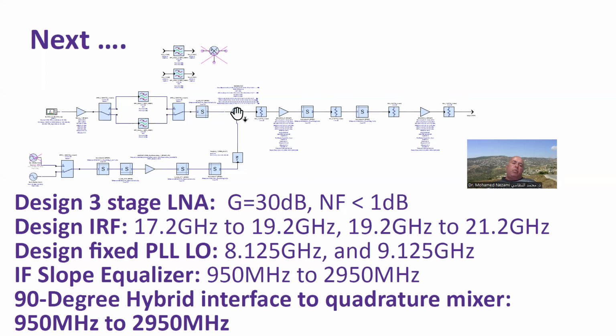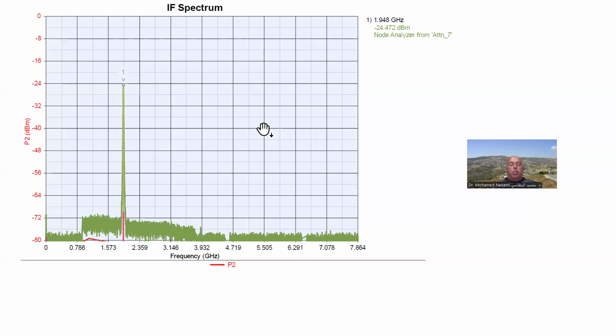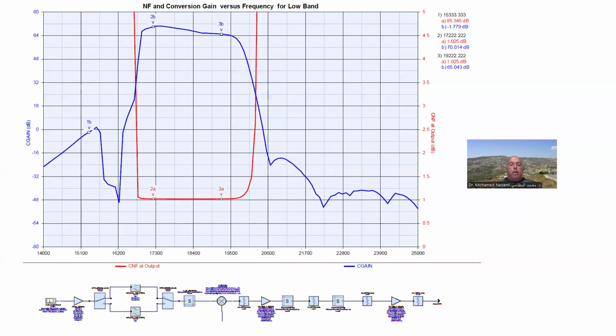First of all, I have to go back and construct the mixer with the actual 90-degree hybrid that I have, because I just don't have the hybrid that they used to measure the performance of this quadrature down converter. So I need to build that model and verify it with the hybrid that I was looking at earlier, or some variant of it.